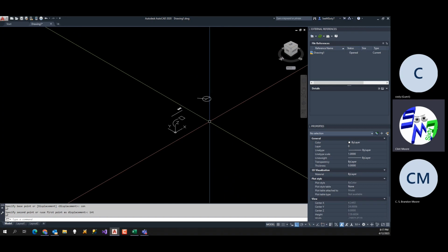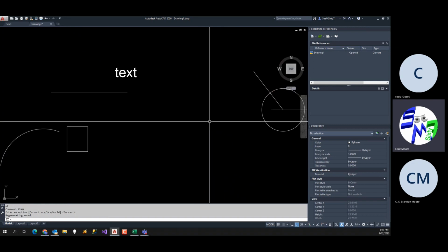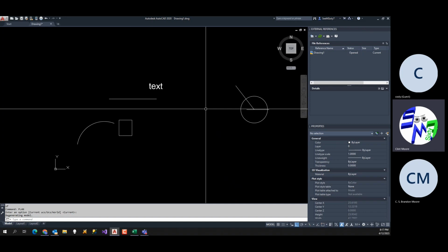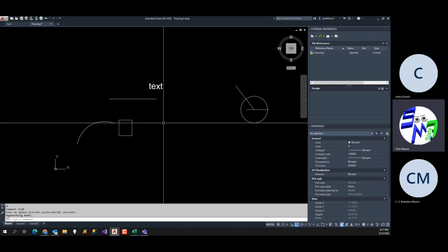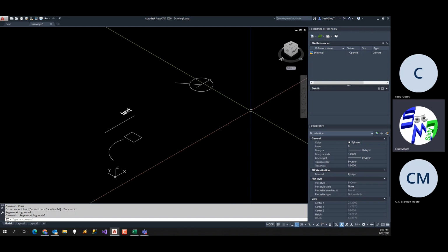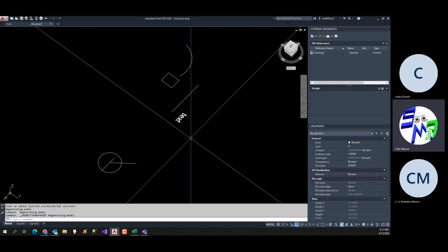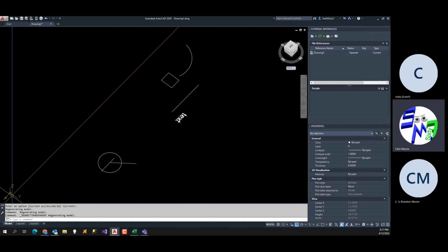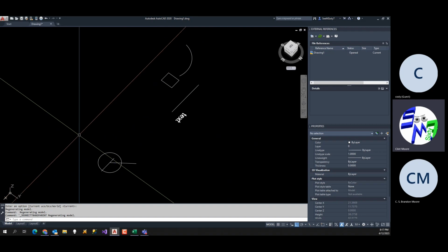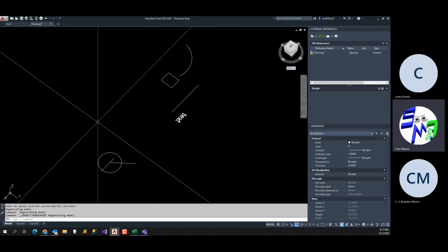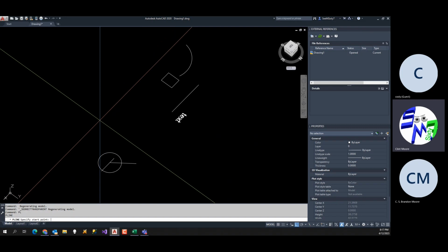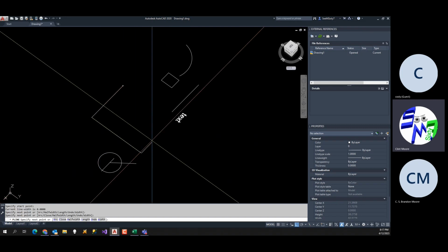Now, I'm typing in plan and then hitting enter to go back to my world view right here. All right, so it's nice, my plan view right there. So if I get on my isometric here, or I start dragging around and I'm like, where am I at? I don't know how to get back to my regular thing. My Y is pointing down to the right, my X is pointing down to the left, and Z is kind of up this direction. And I'm all kind of squirrely. I can't really draw this way. I can. You can just start drawing P line, boom.